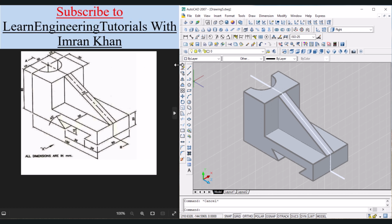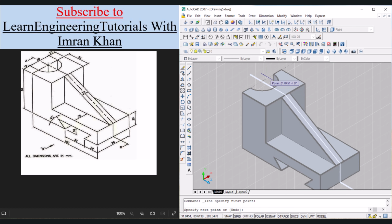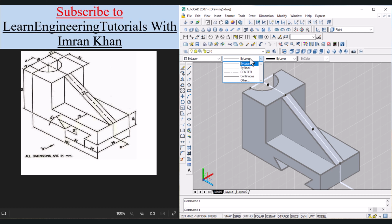Yes, we have to draw another line. Click on line from this endpoint to that endpoint. Press escape. Now select these three lines, and then from this property second box, click on center. Press escape. So the line is center line now because we can see a dash over here, right?